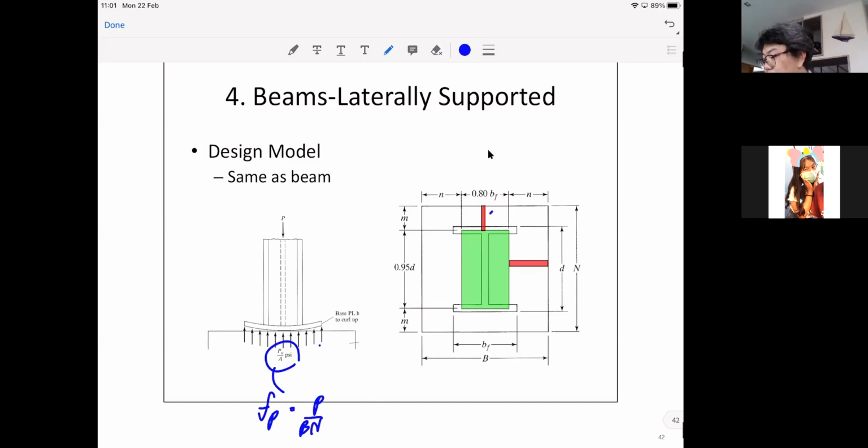Now we have two dimensions, okay? We have the cantilever on both axes. So naturally, you would want to try to make these two distances not so much different from each other, because let's say if you put one distance much bigger than the other, that would become the governing scenario for the thickness of your base plate, right? So it's not very efficient.